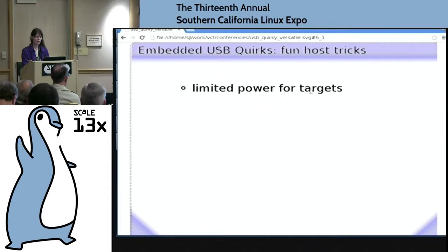And that's actually by design, because people don't want, yes. Well, I have that experience with the Raspberry Pi, but there are some boards like the Voodoo that come with like a 7 to 14 volt power brick, and it pushes 3 amps or something. Should you be able to power a couple USB devices? That was me saying nearly universal.